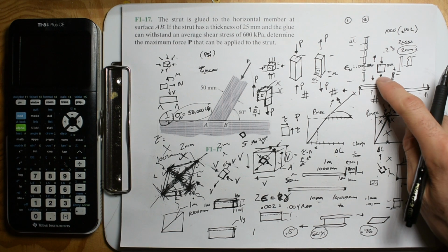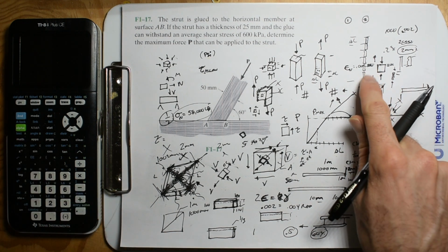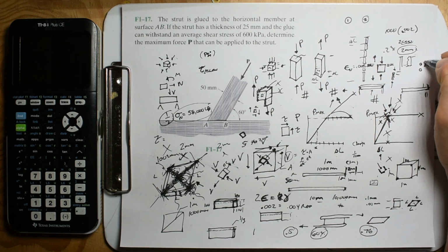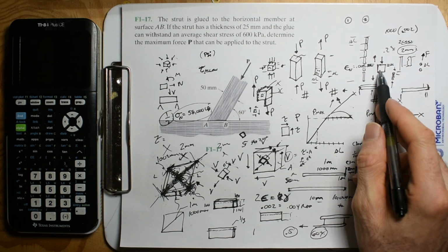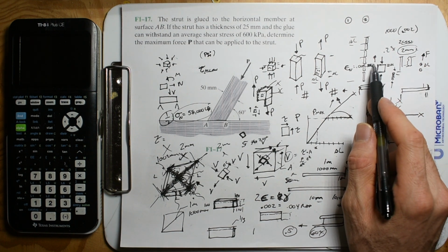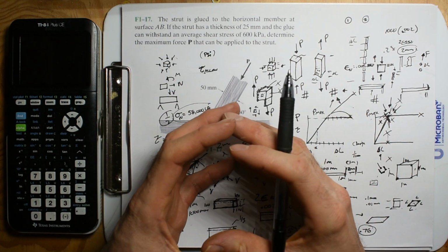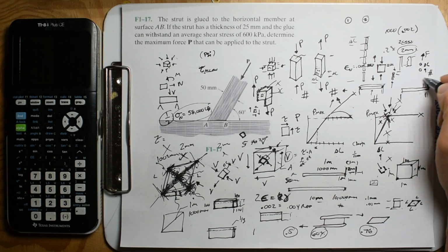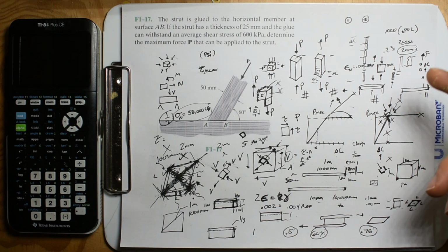But those two don't have to be synonymous. You might be able to change something's length quite a bit, but it doesn't take much force. So don't quote me that concrete and rock are strong; they're very weak in tension. That doesn't mean it has anything to do with the change in length being a big number or a small number. That's where the empirical aspect of material mechanics comes in.